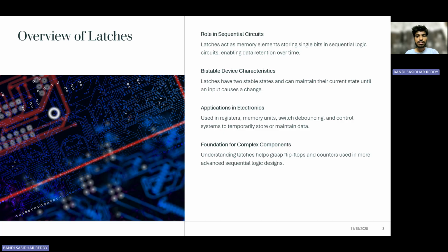They are bistable devices, meaning they have two stable states and can maintain a state indefinitely until an input triggers a change. This property makes them essential for applications requiring data retention such as registers, memory units, and control systems. Latches are typically constructed using logic gates and are sensitive to input changes, making them suitable for tasks like switch debouncing and temporary data storage. Understanding latches is crucial for grasping more complex sequential components like flip-flops and counters.